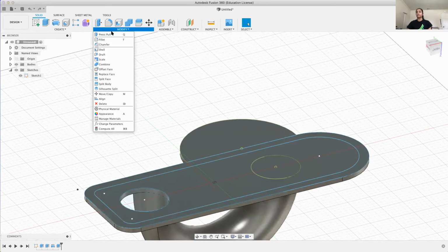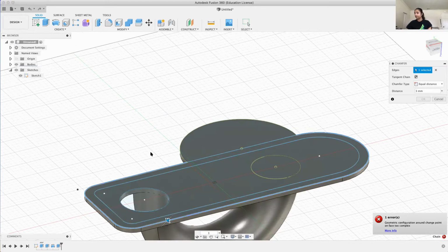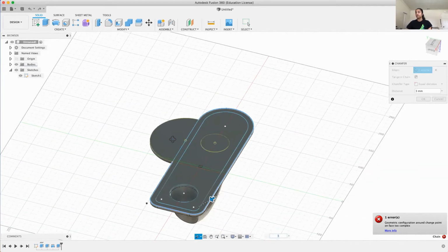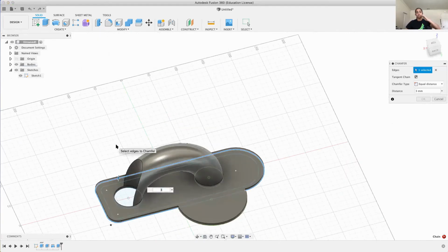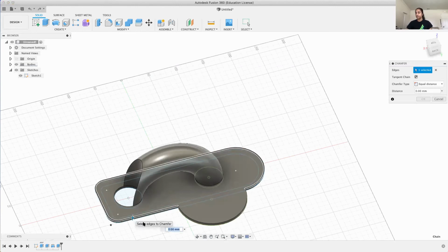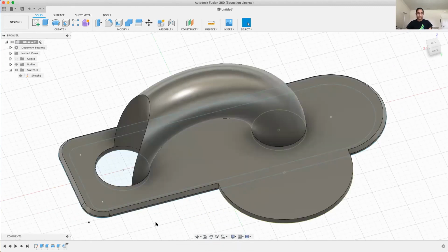There's also another kind of thing you can play around with that is not quite a fillet, but it operates similarly. It's called a chamfer. And so I put that here on the bottom. Essentially, what a chamfer does is it creates an angle, almost like a triangle or an angled cut on the top of the object so that it's also not as sharp.